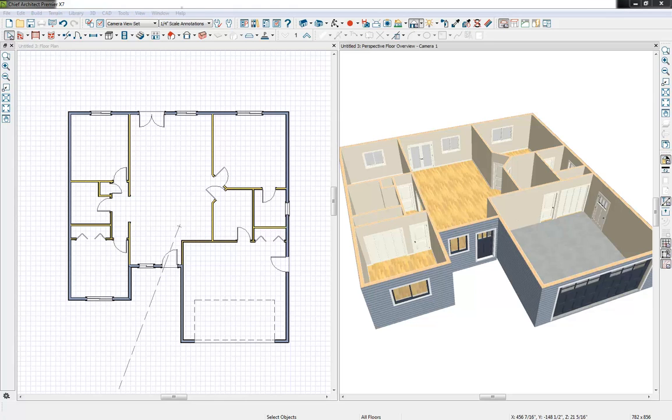Now before we start to change our wall types and set up some wall types, I do want to just show you quickly some default settings in the program. And something that tipped me off here is that the plan that I started this with has a default of a 9-foot ceiling, and I just happened to notice the relative distance between the top of my door and what would be the ceiling here. And I want to go in and change for this plan what the default setup is for the floor. That would include the platform thickness, it would include the ceiling height, and so forth.